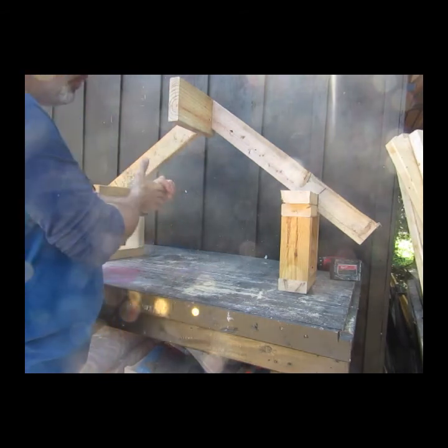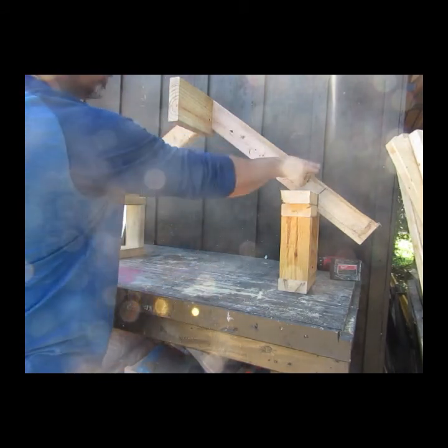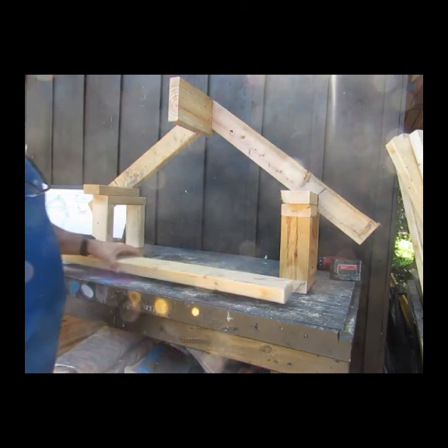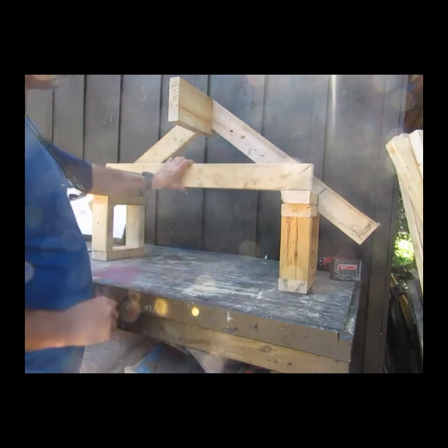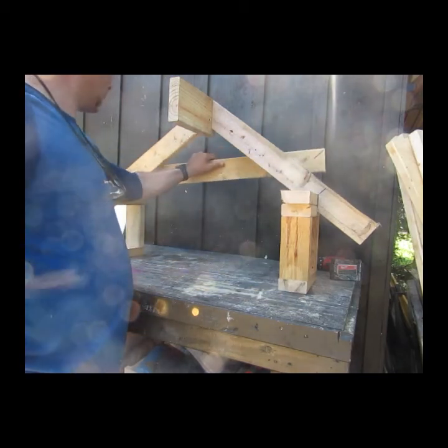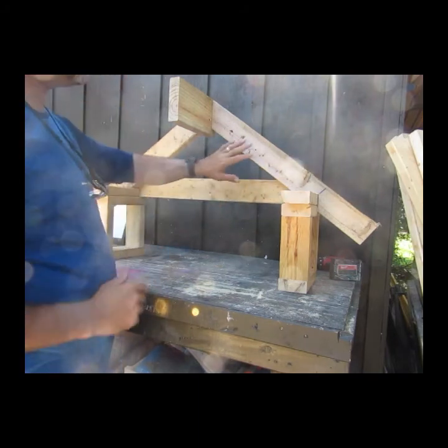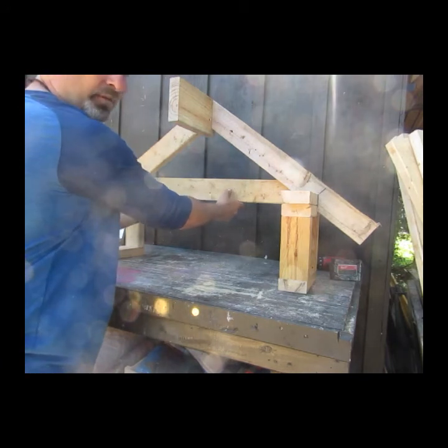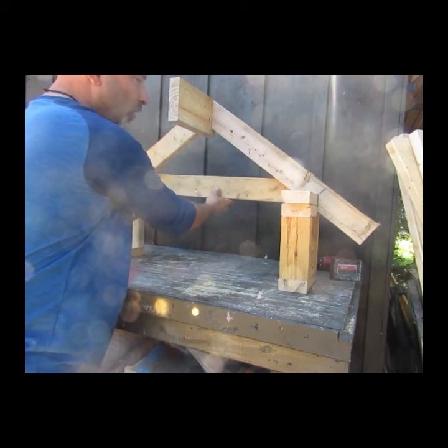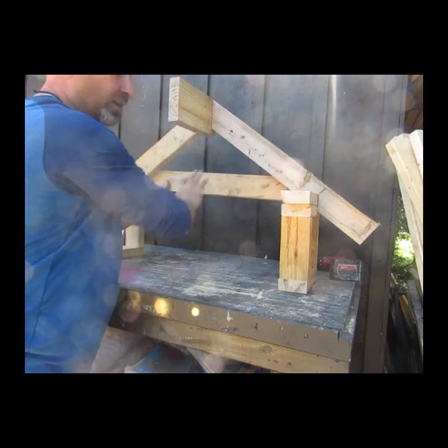So now, to finish off with the bird's mouth, what we've got here is a rafter that goes all the way across. And what we would put in place at the end would be a rafter tie. I'll put this in the back so we can see what we're doing here. That'll just fasten to the back of these, at the bottom third, just like we talked about on my little drawing. This would be fastened across here, or you could cut it on an angle and fasten it in place with a gusset.